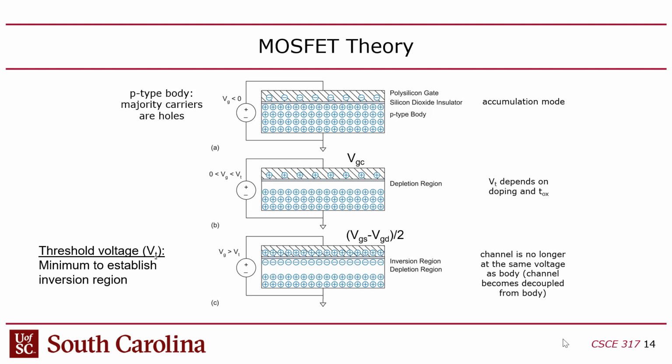Silicon dioxide does not conduct electricity at all, right? Because it forms a crystal, but there's no opportunity for charge carriers to move through it. If you have pure silicon, then you have charge carriers that can move throughout the lattice. It's a little confusing: silicon dioxide is a pure insulator, silicon is a semiconductor, and then you've got the polysilicon, which is silicon with a very high doping to make it as conductive as possible.